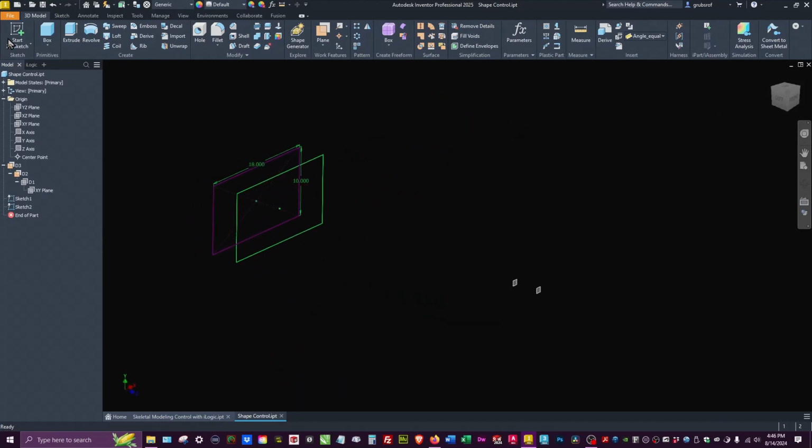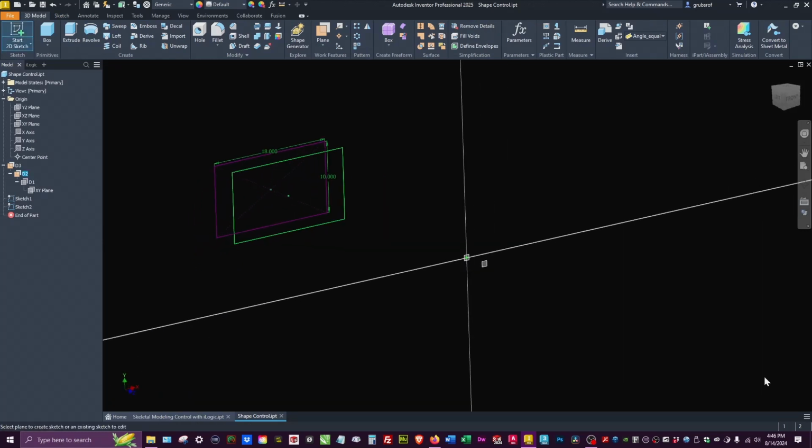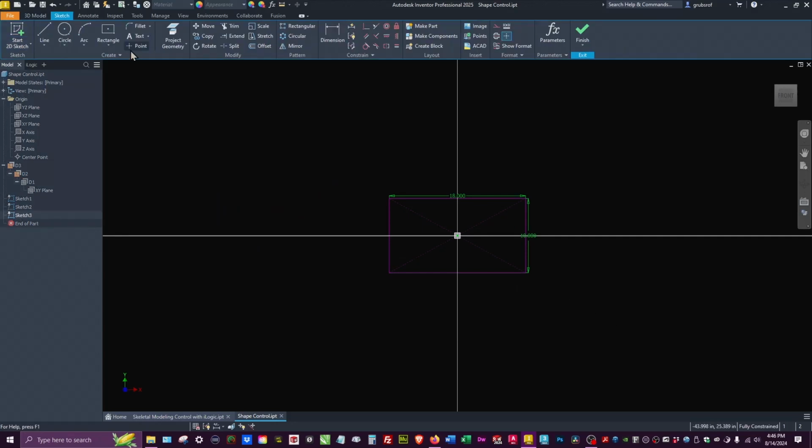Our next one is going to be a larger shape, but this is going to be a little different. I'm going to start out with doing it off center. I'm just going to do an arbitrary location, and this is going to be middle, so that's what I'll put. W for width. This is going to equal, and this is going to be 33. Hit tab to stay in the command. Middle again. H for height, and this is going to be 22.